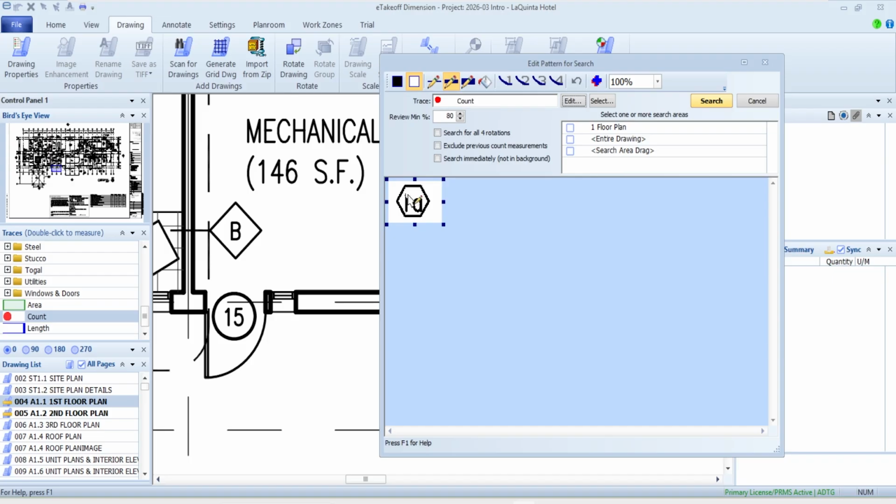I'm actually going to just take this out, because when the system goes off and does a find, like a lot of systems I've seen out there, it'll search for a symbol, but if you find out that's not really the symbol I want, I tell it that I don't want to count it, and then I come back and do a search later for another symbol type. So what this allows me to do is look for this basic shape once and maybe use that many times. I got a little carried away on my taking out here. And that's going to be close enough for what I'm looking for.